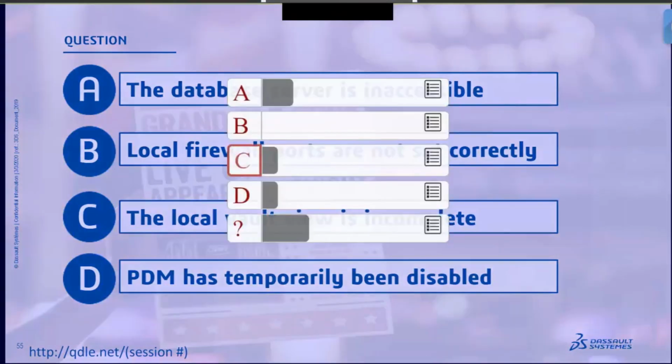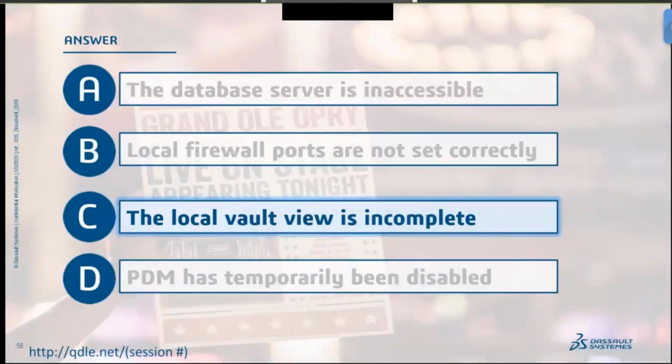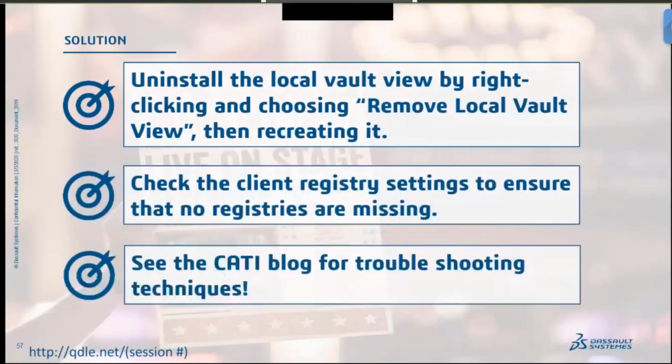All right, so the correct answer on this one is actually C, the local vault view is incomplete. If we take a look at what can cause this, this is something that has to do with your local machine. So the best solution is to try to uninstall or remove the local vault view. This can be done by right-clicking and choosing Remove Local Vault View, and then recreating it.